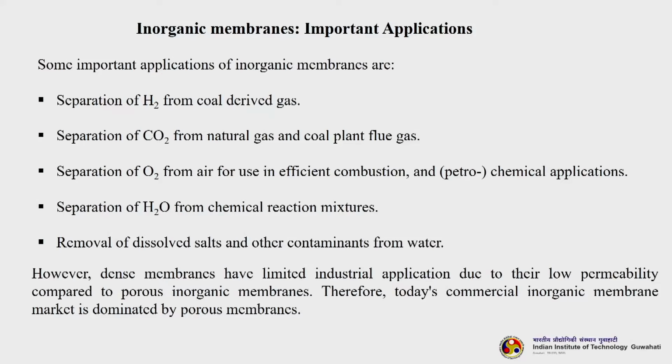So, some of the important applications of inorganic membranes which I have listed here are separation of hydrogen from coal derived gas, then separation of carbon dioxide from natural gas and coal plant flue gas, separation of oxygen from air for use in efficient combustion or petrochemical applications, then separation of water from chemical reaction mixtures, removal of dissolved solids, salts and other contaminants from water.